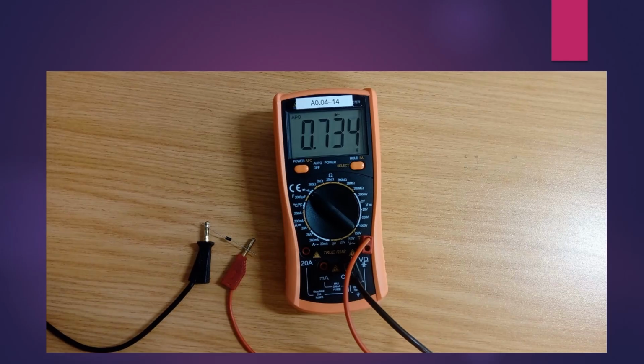And then on your diode, your red lead is on the anode, your black lead is on the cathode, as you can see, and the value that's displaying there is 0.734. That's the value of your diode. It should be between that 0.7 and 0.6. So if I were to change those leads or to swap those leads, then I'll be getting OL. That's how you measure your diode. I hope you guys can see that.